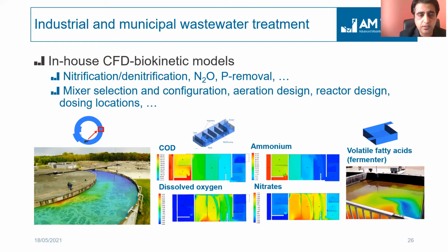And these kinetics can be any kinetics. It doesn't have to be only nitrification or denitrification. It can even be N2O, or bio-P removal, together with the hydrodynamics of the CFD. What we can achieve with such simulations is that you can first really look at the impact of your configuration on the performance of the process, and then by tweaking, for example, you can choose a better mixer, or a different mixer, or place it at a different location, and see what would be the impact on the performance of the process. You can have different aeration designs or entirely new reactor designs, or, in the case of chemical dosing, have those applications evaluated with respect to how the process will perform. So this opens up huge possibilities in that respect.